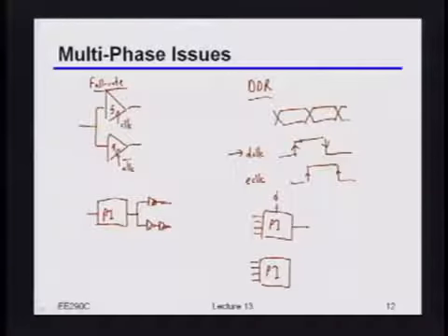So let's say this is some phi, I can make this phi plus 90, right? And then indeed, I'll get 2 output clocks, which at least nominally would be separated by 90 degrees. Okay, so this works. By the way, there's some people that do what's called QDR, which means the clock is 4 times slower than data.